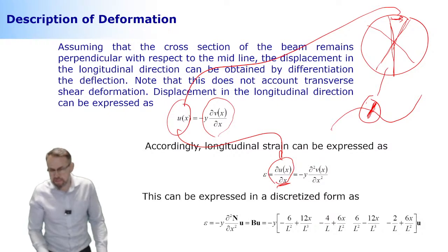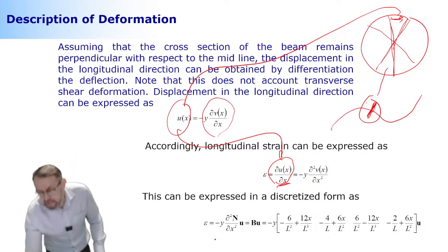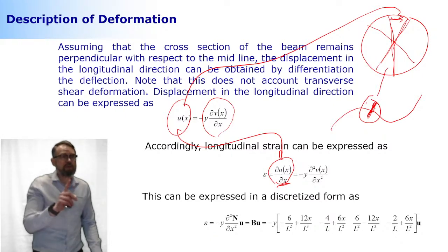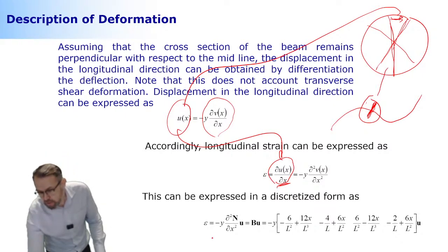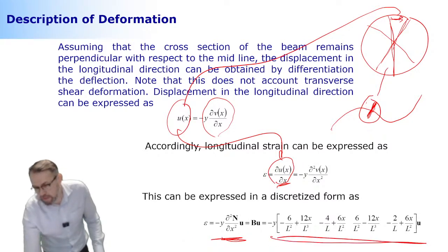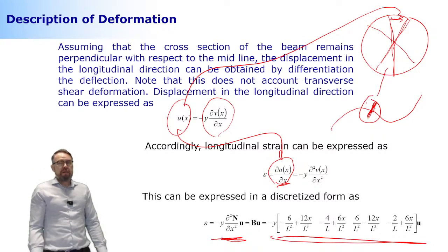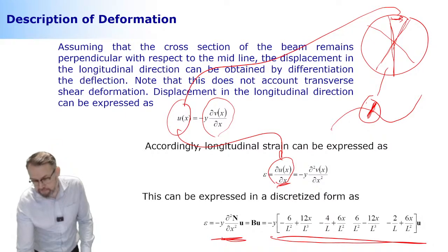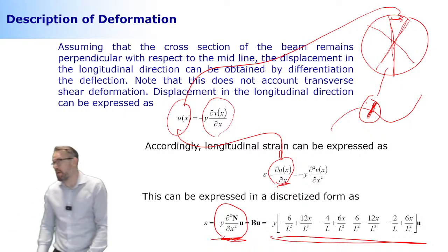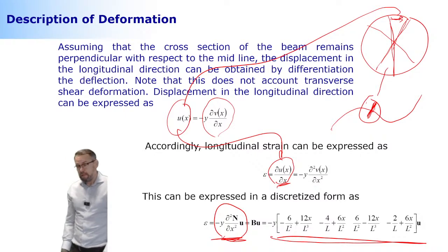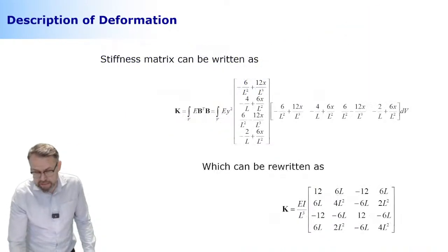You can get at this by differentiating the shape functions twice with respect to the x coordinate axis. Once you do it, it's going to read like this. This is pretty much the most cumbersome thing to do. Again, it's differentiating the shape functions twice with respect to the x-axis. Very easy to do if you're using a symbolic math tool. That's going to be your kinematic matrix.